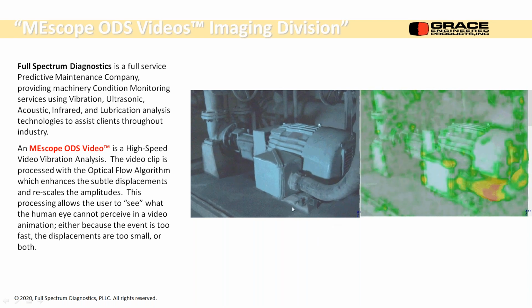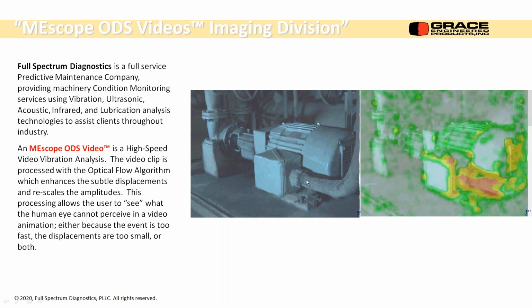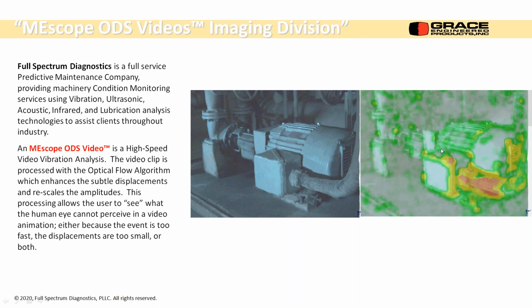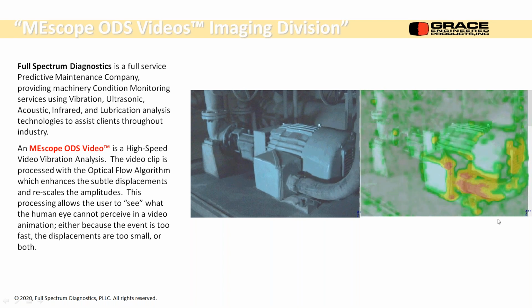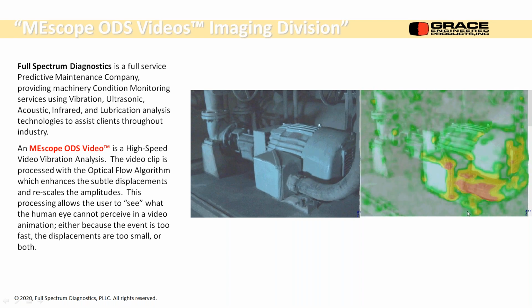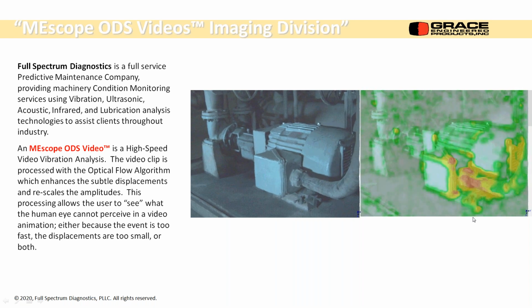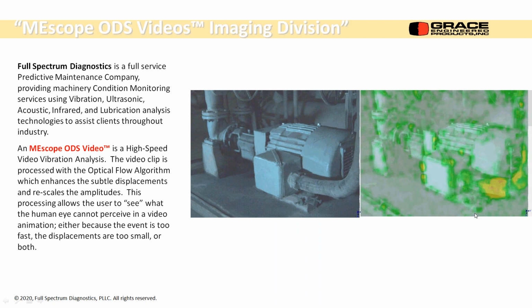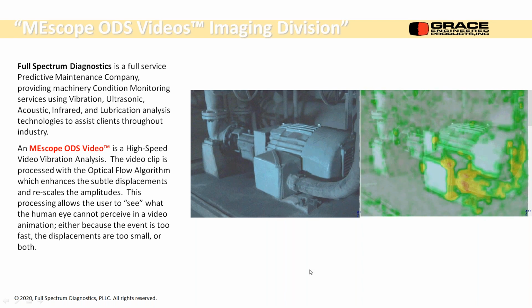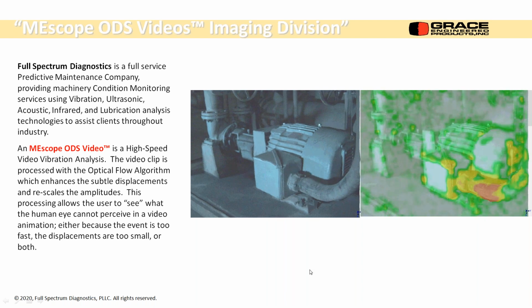It delaminated from the base plate, so it was lifting. So you get this kind of diagonal vibration going in there, and put a little color on it. This should be all gray down here. There shouldn't be any color to it at all. That just tells you that there's some motion there. So the only way we found this was with a vibration video, which was very interesting.